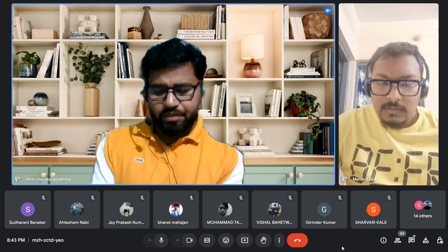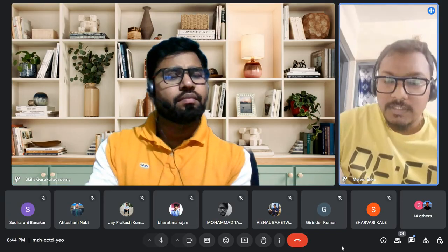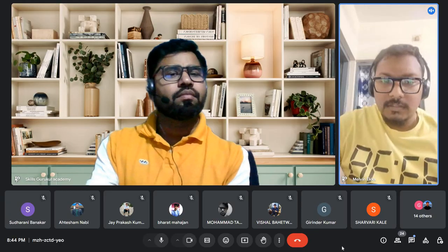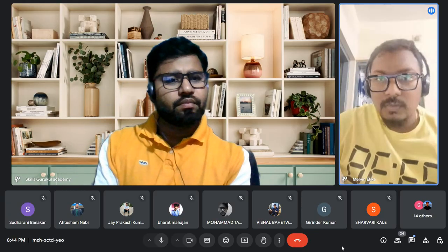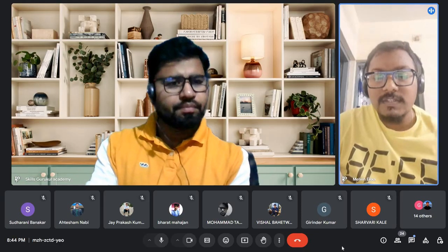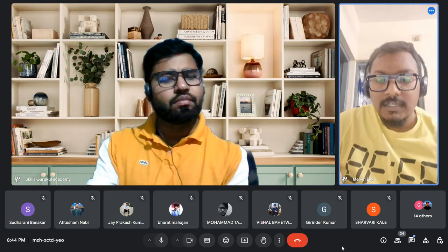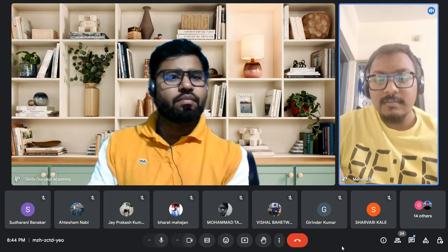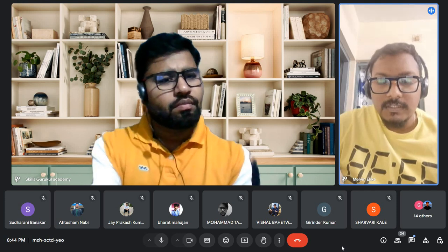Okay, can you give the names also? According to the connections provided, they are riveted, bolted, and welded connections. According to the type of internal forces, it includes shear connections, like semi-rigid and simple connections, and moment connections for rigid structures.